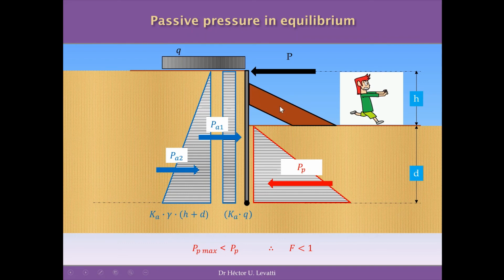So I hope you understood this topic of thin walls inserted in the ground for simple cases. In this case, it's just a soil which is basically sand and without a water table. Remember that in reality everything is much more complicated. You usually will have a soil with several layers, and you will have the presence of water tables at different levels, because the level of the water table will change with the seasons, and actually during the day you can have changes, and you will have to run several calculations in order to be sure that you are in good conditions for every single day of the